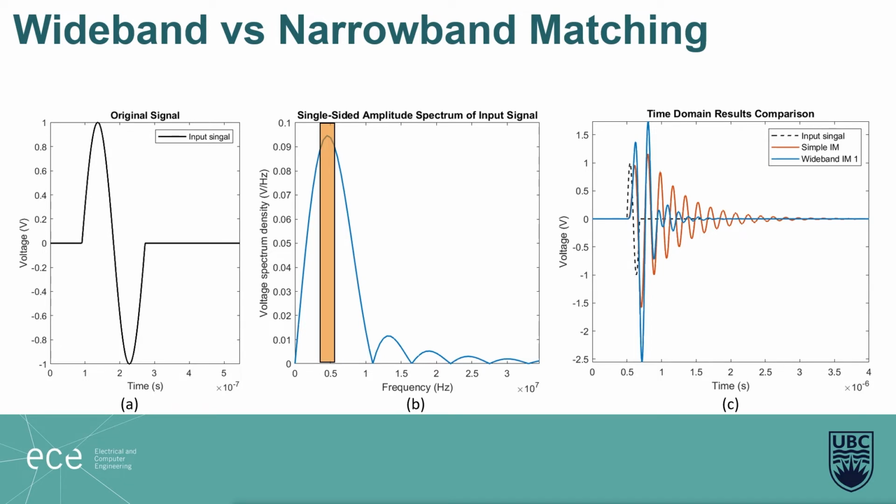This ringing is not a concern in applications where signal reception is not critical. For ultrasound imaging, this ringing will cause undesired artifacts in the image. With our matching, we see a greater peak amplitude and less ringing, just because it is a wideband matching and it covers a wider spectrum.